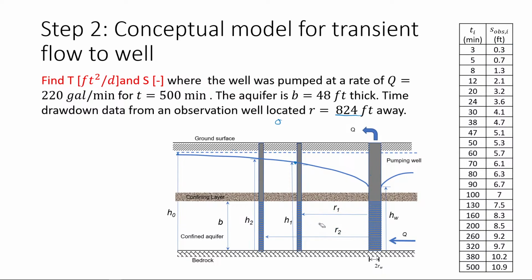So in the field, somebody will be pumping from here, or a pump will be here, and somebody will be standing here, or you have an automatic logger here that will keep recording the drawdown, how your head is dropping down with time, at different times. So that is basically my conceptual model.